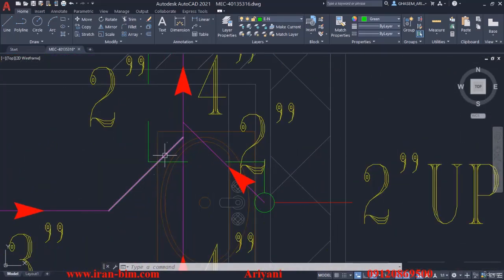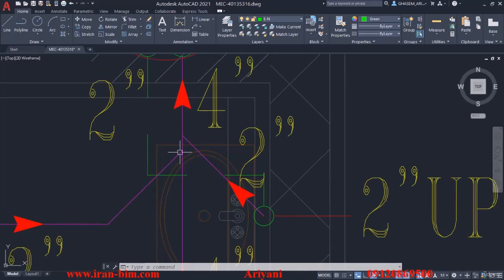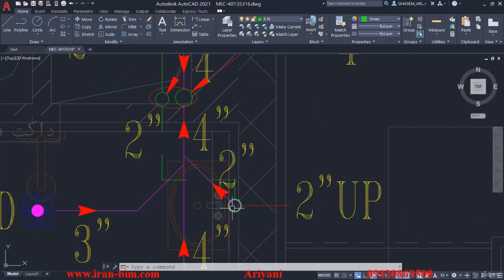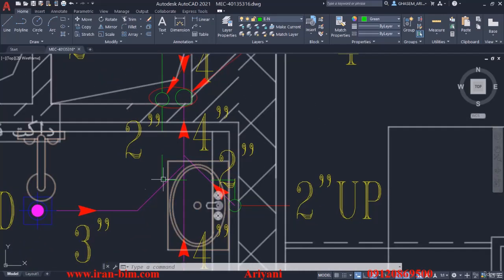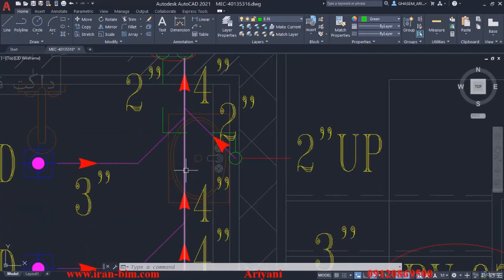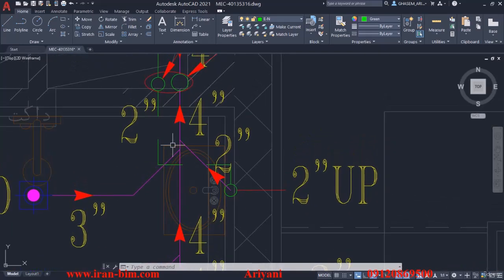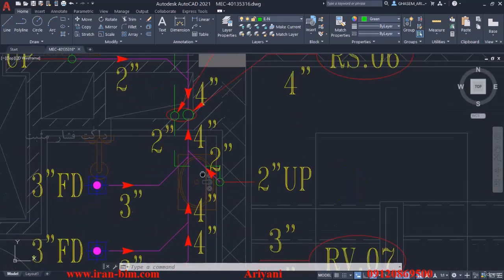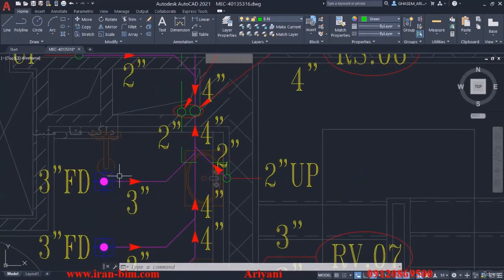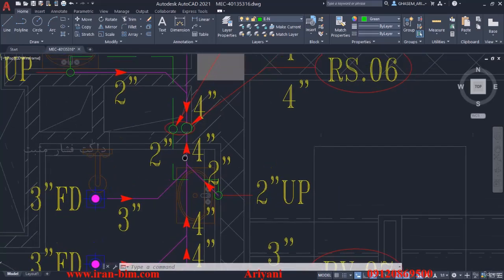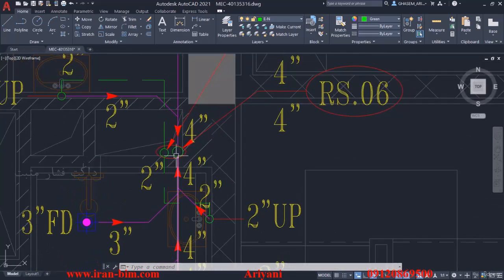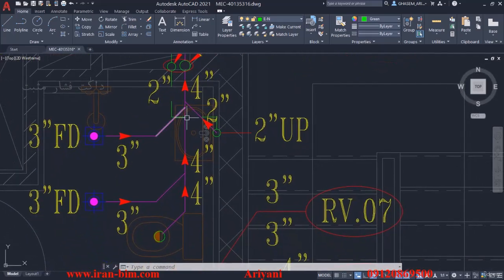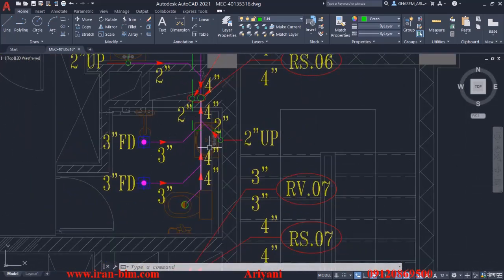But a problem that we have here is that the drain goes from a 45-degree angle pipe to a three-way fitting. Then we have a sink here on the right, which connects to the fitting through a 2-inch pipe. Then we have 3 inches at the left and 4 down. We actually don't have enough space to place 2 three-way fittings here. So we either need to change the direction or connect the drain to the riser from another pipe. And that's the difference between 2D and 3D plans.